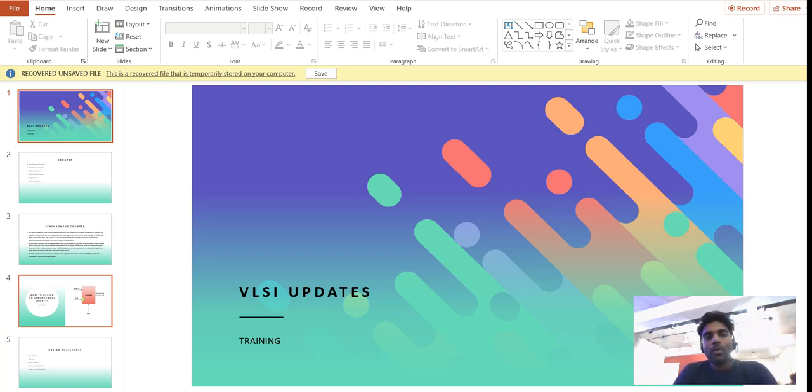It is important not only for smaller designs, even for bigger designs. It's actually good to start from the block diagram, and the block diagram doesn't have to explain what kind of low level circuits are going to be there. Is it going to be a counter? What kind of flops or what kind of resources is it going to consume? It doesn't have to. Just draw a block diagram, have the input and output ports, and you can start defining them before you start writing the hardware description language. Okay, so I just wanted to have that session quickly.